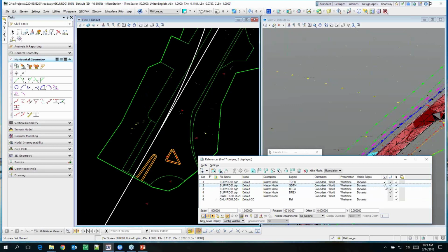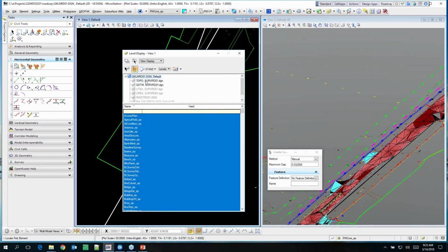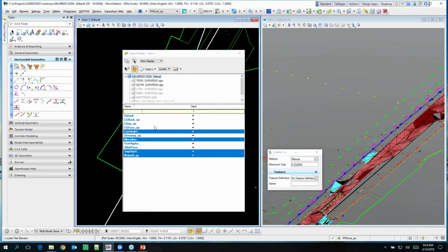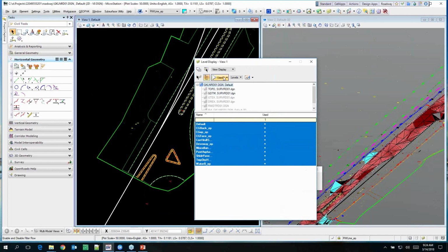So in order to actually get that to happen in a cross section, we can model those lines in our existing feature model, and then when we slice through that 3D line, just like I said, when you slice through a line, you get a point, and for most of the points we put a little yellow dot. For the right-of-way lines, we can change that to a cell, and we have a right-of-way symbol cell. So when you cut through a line that has a right-of-way line feature and view it in a cross-section, it appears as a right-of-way symbol cell. And that's how we get them on the cross sections.